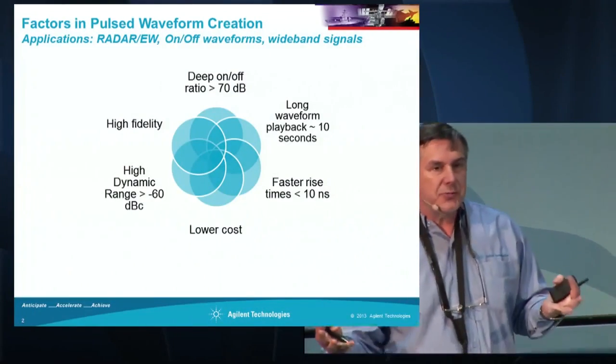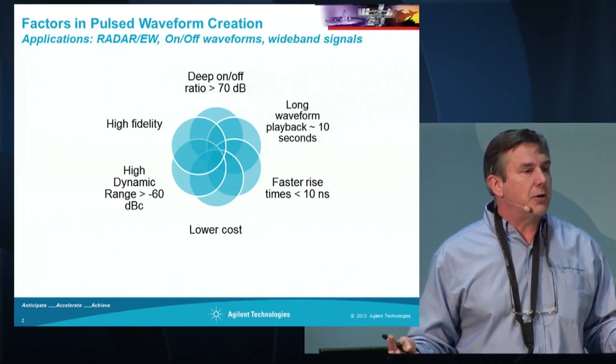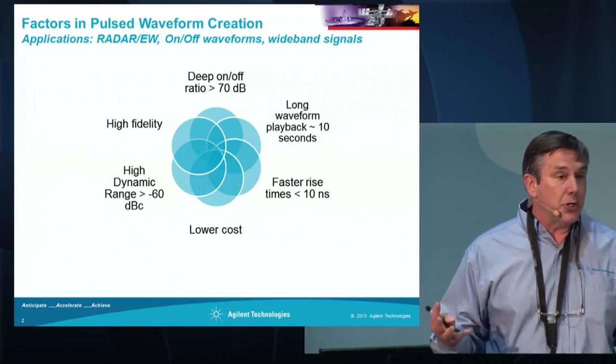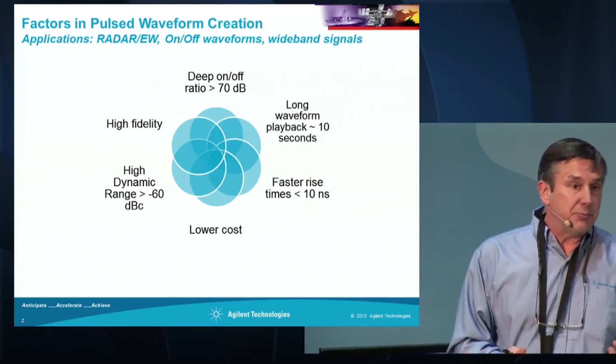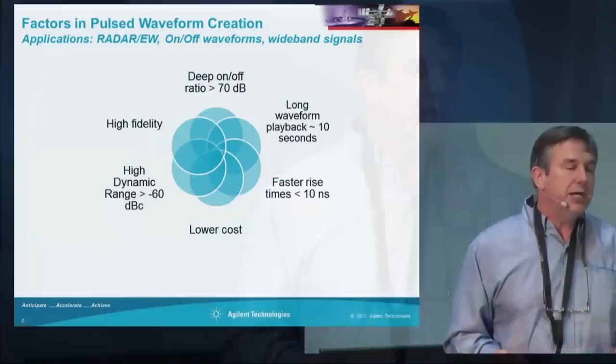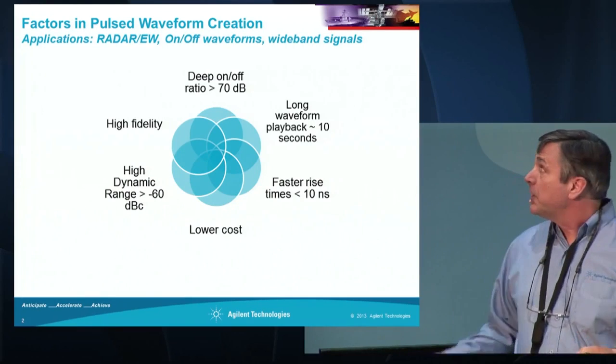Today's radar systems, of course, we're starting to track targets that are moving very slowly. In other words, what are the military terms as dismounts. So these are people who are walking along a trail or even in a busy urban environment. So high fidelity means very low phase noise, being able to see Doppler shifts very close to the carrier.